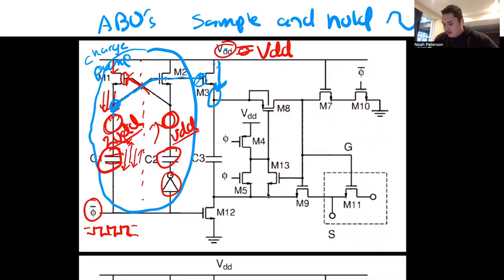That's what the charge pump does, and its job is to pass voltage back and forth, to oscillate it, and it takes a little bit to get to the point where it's oscillating between 2VDD and VDD. But that's all it's doing essentially. By doing that, you have this VDD coming into this part of your circuit, into this C3.